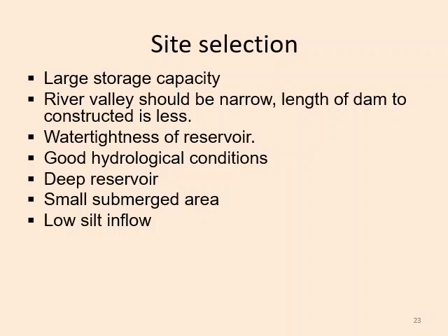Silt deposition is a problem in a reservoir. The storage capacity will get less then. So the silt coming with the inflow water should be less in quantity. For that purpose, small hydraulic structures, silt excluders, etc. are generally constructed.